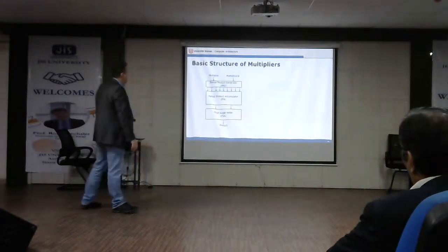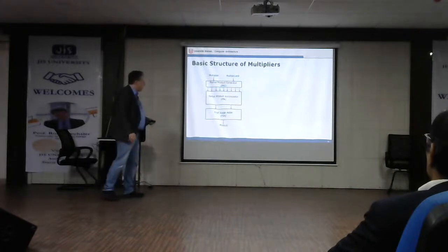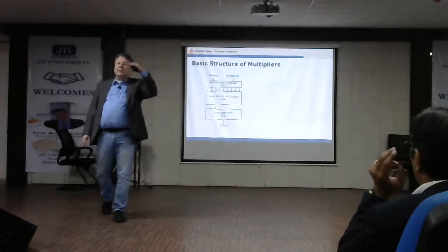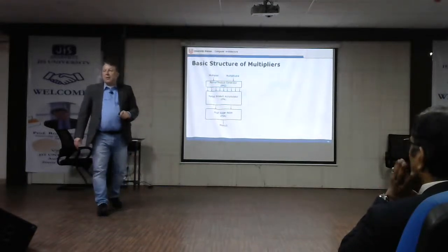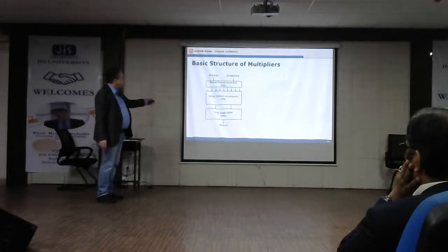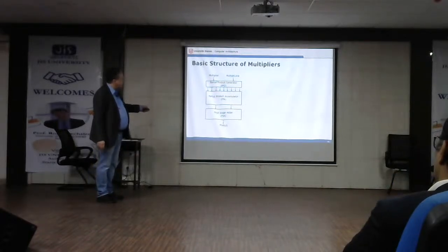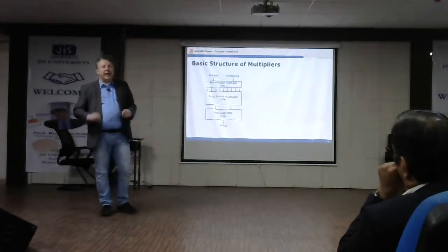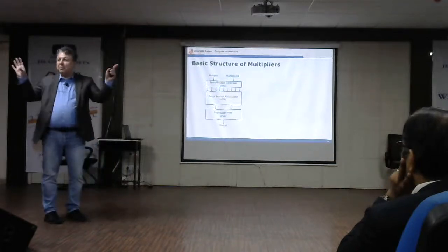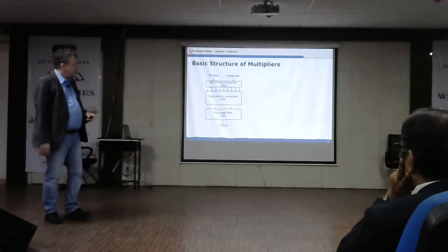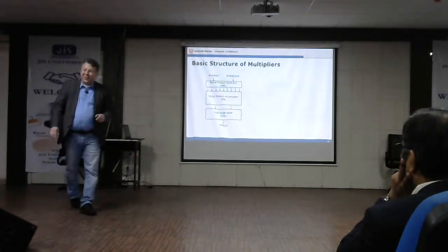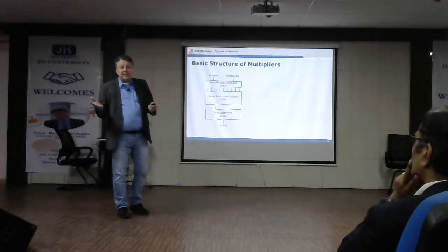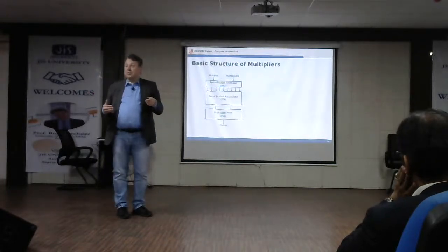Whenever you have a lecture on multipliers, on how to design multipliers, typically multipliers have some kind of 3-stage structure. You first generate partial products, you add up the partial products, and you have a final stage adder. That's the typical way. Some of you might know these architectures. As for the others, just believe me. I know what I'm doing. And how the different multiplier architectures differ is essentially how you build these 3 stages.